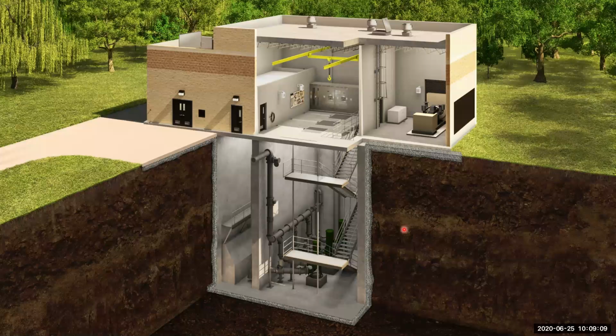And just to help clarify the previous slide, this is a cutaway rendering of a wet well, dry well style station for one of our projects. And this area here is the wet well. So this is where the wastewater is collected. And then on this side of this wall, you've got your dry well. This is where the pumps are housed. And you see you've got suction lines that draw liquid to the pump, and the pump then discharges into the force main and down the line.